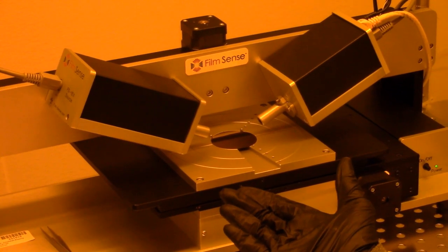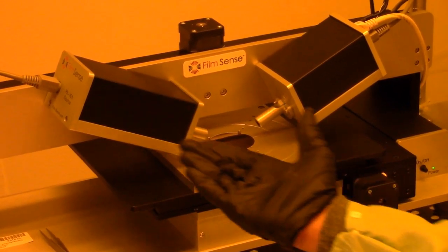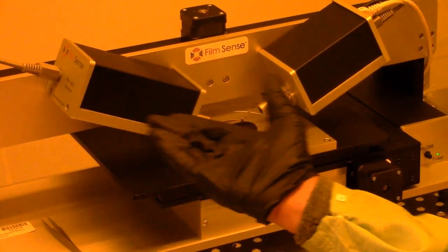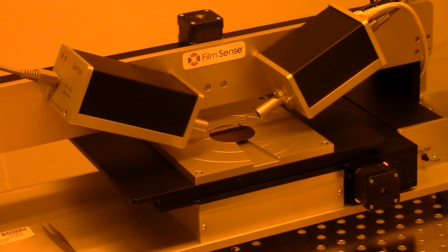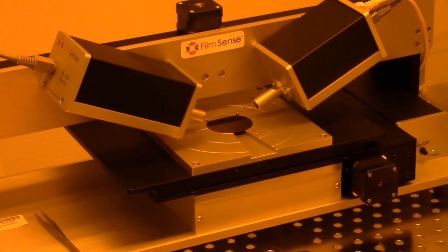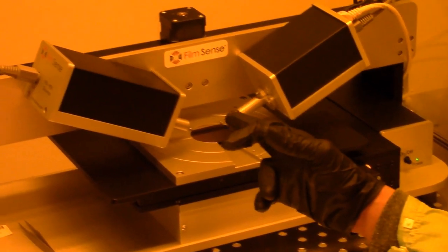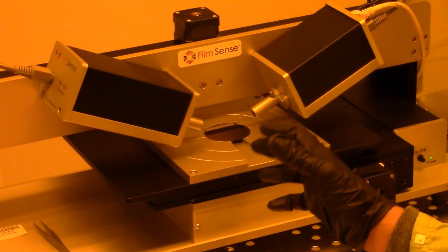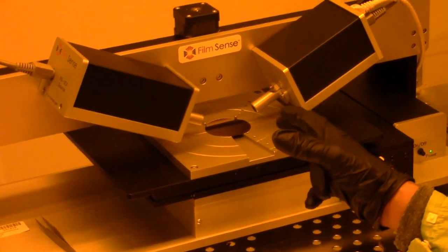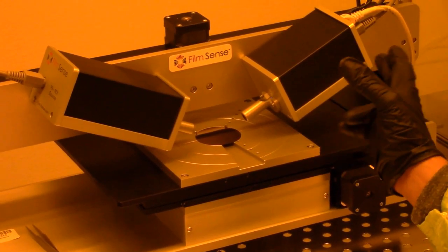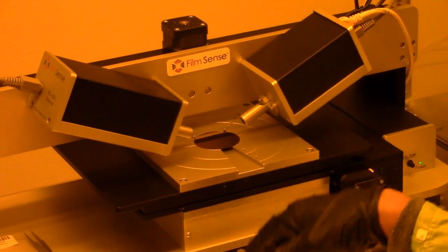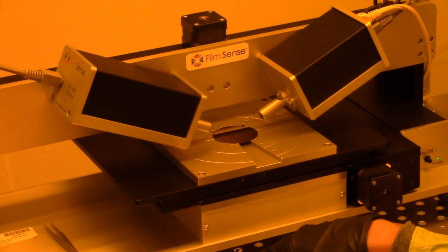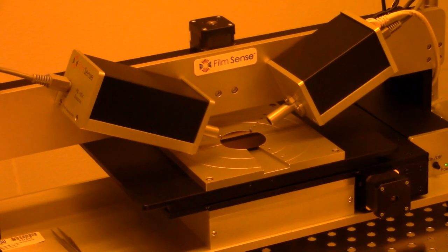Essentially, an ellipsometer operates by having linearly or circularly polarized light incident at a certain angle onto your wafer using the incident polarizer, and the incident laser beam comes out as elliptically polarized light, which is detected by the receiving polarizer and resolved into an amplitude and a phase component, from which you can deduce the refractive index and the thickness of your film.